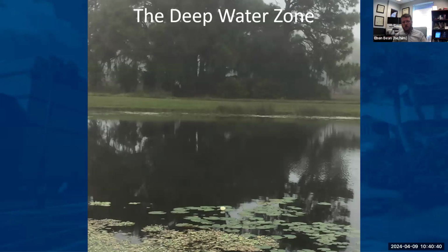And so these deep water zones can be great for supporting habitat of fish that can help to manage algae as well as provide diversity of habitat in this environment. I also want to say that stormwater ponds that have algal blooms is not necessarily a bad thing. We don't like to have severe algae blooms, and that can maybe be managed by trying to reduce the nutrients that are coming in. However, small amounts of algae or slight coloration is pretty natural. We want the algae, if it's going to take up nutrients and process nutrients, to do it in the stormwater pond rather than in the downstream water bodies, right? We're not intending for these stormwater ponds to be natural lakes that are clear water systems. These stormwater ponds are intended to treat water, okay?